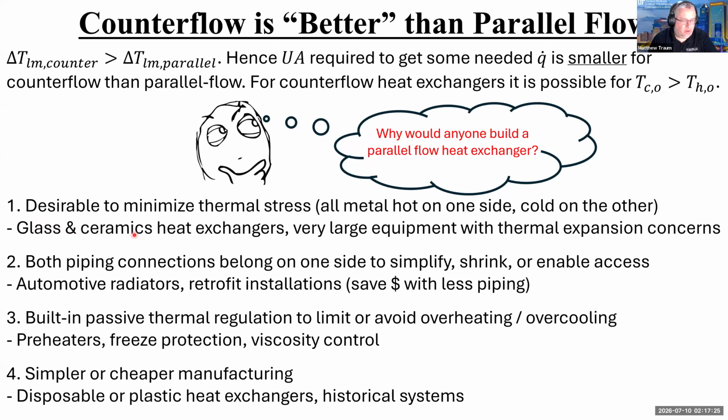I don't do it in my fluids class, but I actually have a still, a chemical still, right? Not for making alcohol per se, but for distilling chemicals. And all the heat exchangers, because it's chemical lab equipment, are made out of glass, and they're all parallel flow, specifically for this reason: we're trying to minimize the thermal stress in those heat exchangers, because glass is very brittle and breaks if you put it under substantial thermal stress.